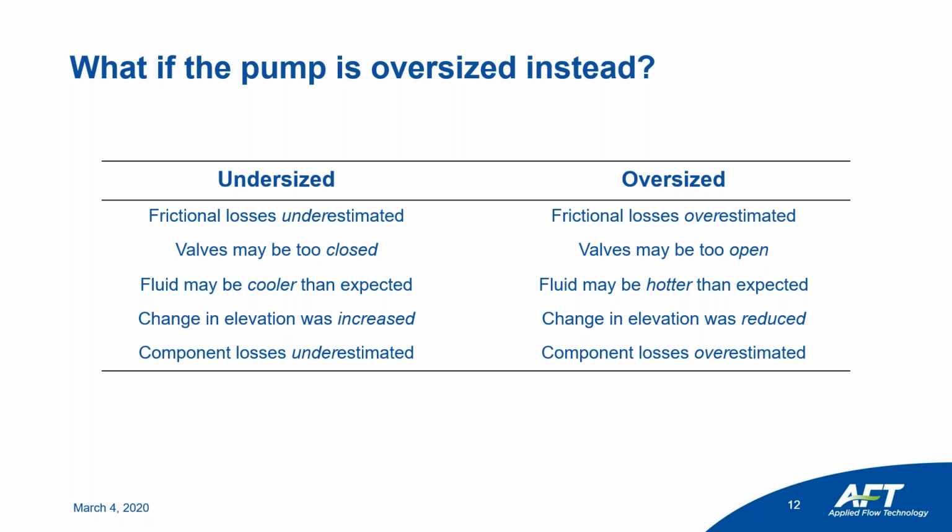And then finally, we can also look at component losses. That kind of folds into the frictional loss aspect. And so that's kind of the pump operation portion of this webinar: the importance of BEP, why you should consider the preferred operating region, some things to consider if you notice that your pump's deviating, and how you can test those things in Fathom from the comfort of your desk.